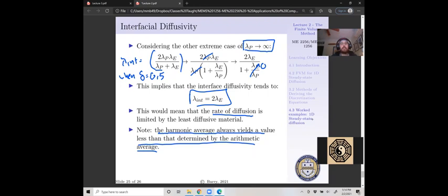Now, you will see on your first homework how to use these two types of averaging techniques. And what you're actually going to see is you're going to get pretty reasonable results by using both. A way to overcome this is we just put more control volumes, more cells within our model. You also get to play around with the insulating boundary condition. So that rounds out everything we needed to cover from lecture 2 about our one-dimensional steady state diffusion equation.